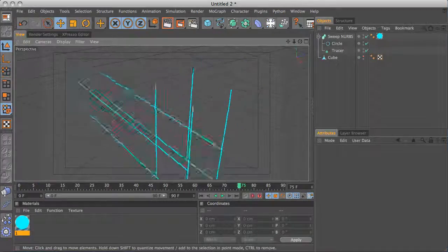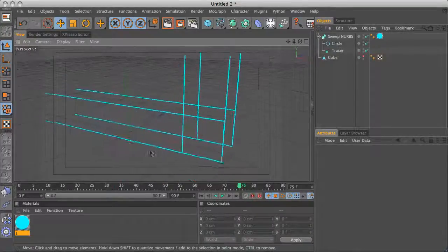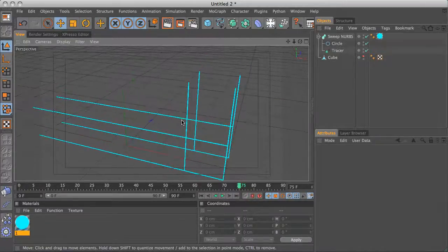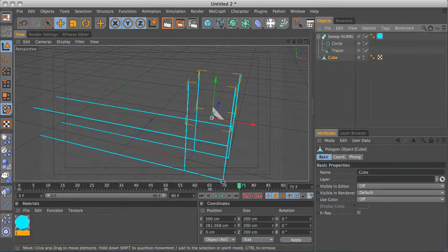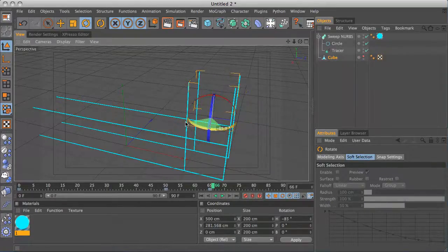So this is quite a good method of creating a nice framework, and there's no reason why you couldn't do something like, for example, let's take our cube at that topmost point there, move forward 1 frame, actually let's move back a frame, add a rotation keyframe, move forward 1 frame, and then just rotate it by 90 degrees and keyframe that.